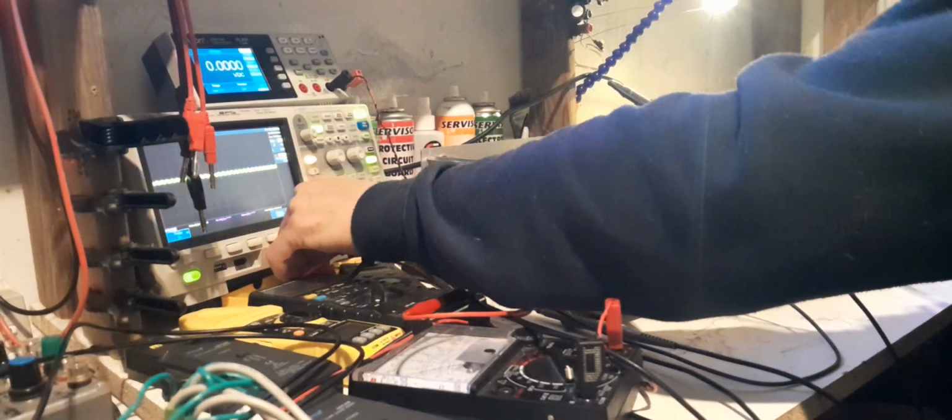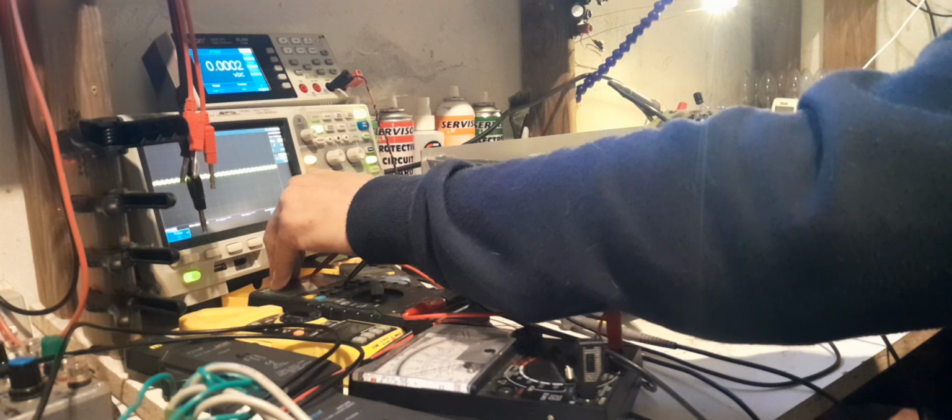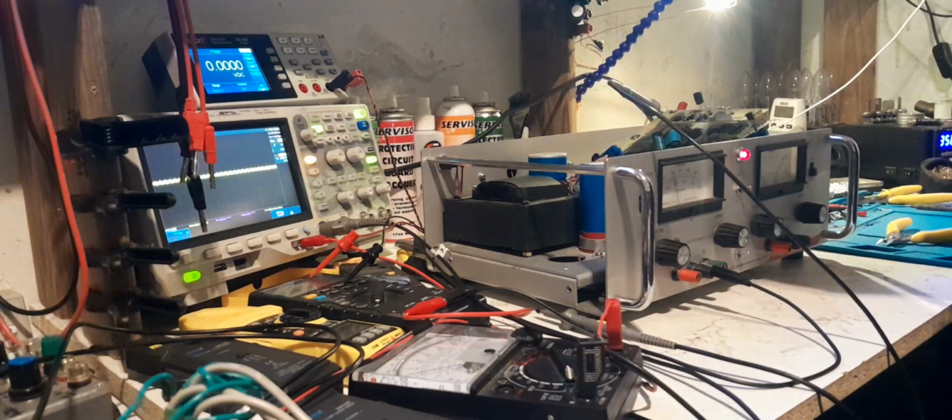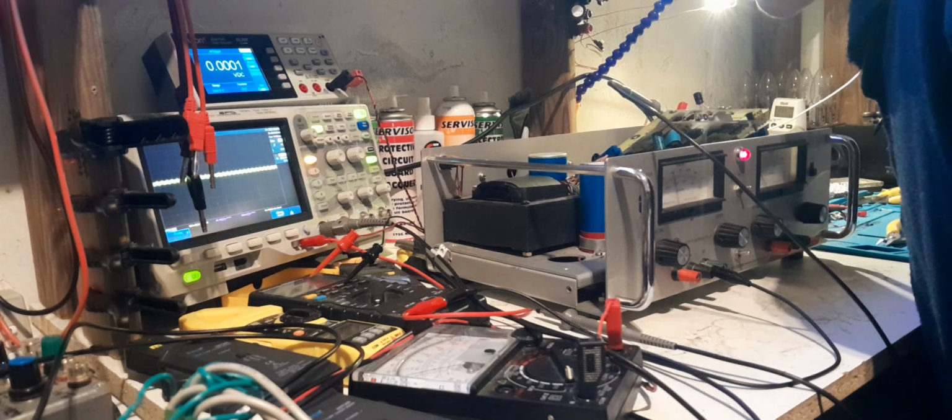I think I might still have another problem here. Because the peak to peak was exactly 20 millivolts and the RMS was 2 point something, about 2.5 millivolts. And now I've got 1.33 millivolts RMS and in between 18 to 182 millivolts peak to peak because of these huge spikes that are just randomly appearing. They definitely weren't there before.